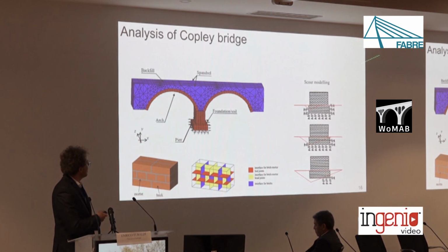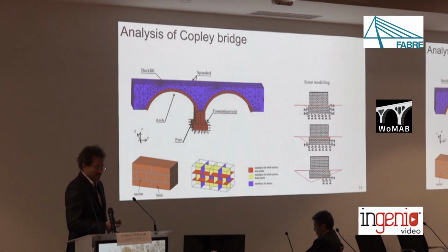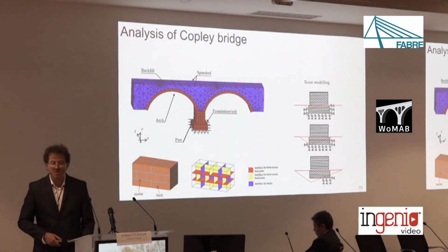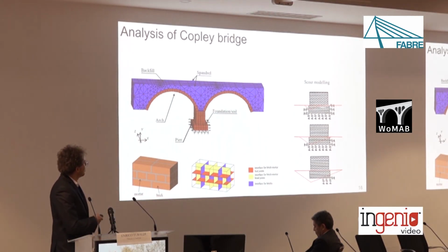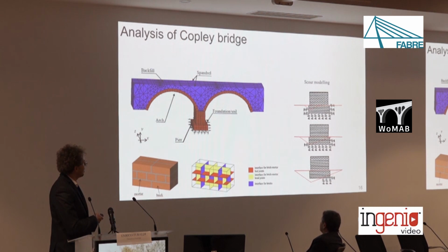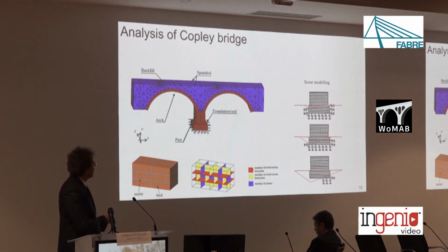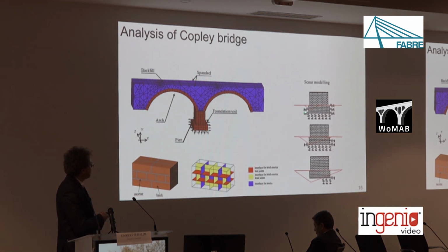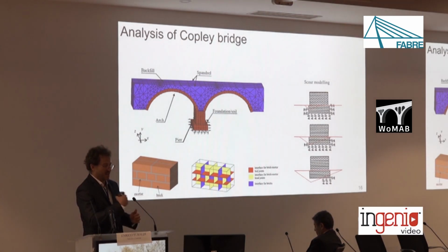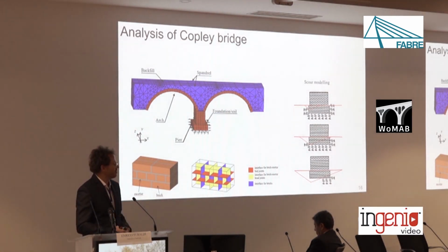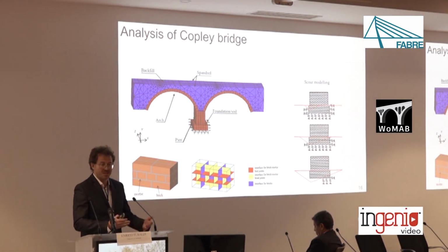And for describing the problem of the effect of scour, we resorted to a Winkler type of approach for soil structure interaction. So you have a series of springs surrounding the foundation, and scour is simulated basically by removing those springs that fall inside the scour hole. In a time history analysis, basically, with a staged approach, these springs are progressively removed.